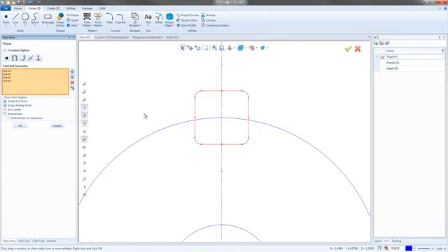It can be a lot more than you need. You know, if I was just trying to find where one of these points is, this is overkill. So if you are just trying to find a single point, or maybe just a couple, use the point sketch function, because then you can sketch and snap points wherever you want, and they'll jump onto the snap point, so it automatically jumps there.